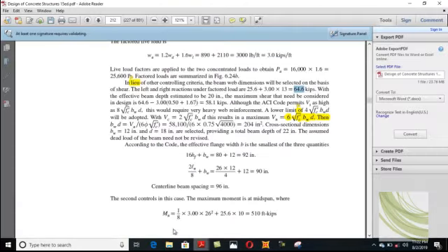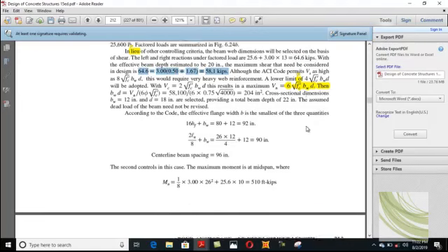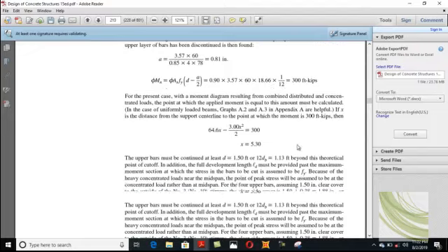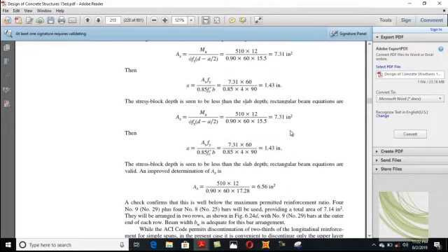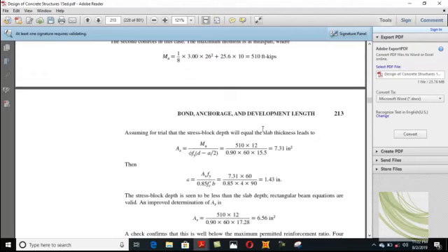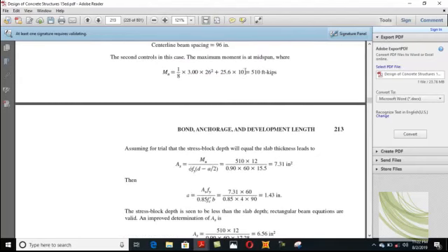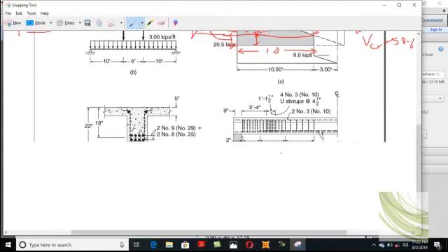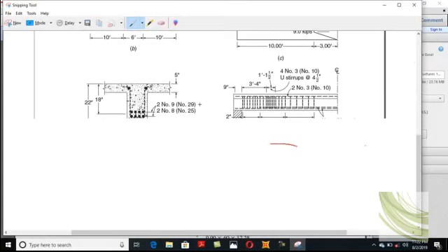So a little bit confusion is in this point here. Okay, so I think now it is clear. And there is also a kind of confusion. I take this distance equals to 13 feet. So you must know that in this case the maximum moment diagram will be somewhat like this. This beam is basically a simply supported beam, okay, and it is subjected to UDL plus 2-point loads.